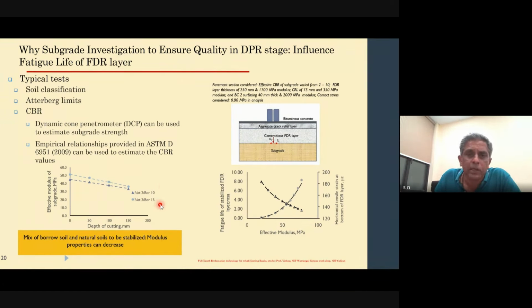If you add more cement, the strength will go up, and as a result you end up having a material of very high strength, and there might be other problems like shrinkage and cracking. Now, if the cement content is different or the strength is very low, then you may end up having a section that has a poor load carrying capacity. So the technique of a mixed design is actually to maintain a certain level of strength, but not too high or too low. That is where the challenge comes in, considering that the materials going into this particular work have a lot of variability in them, like what I have mentioned earlier, the big bars, the size differences, all those things.